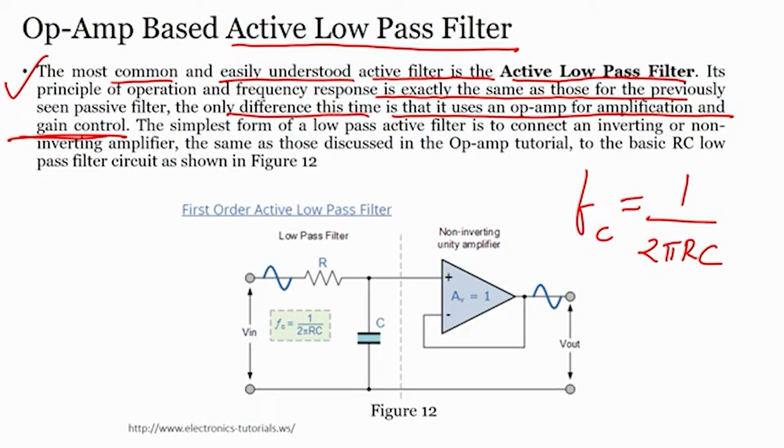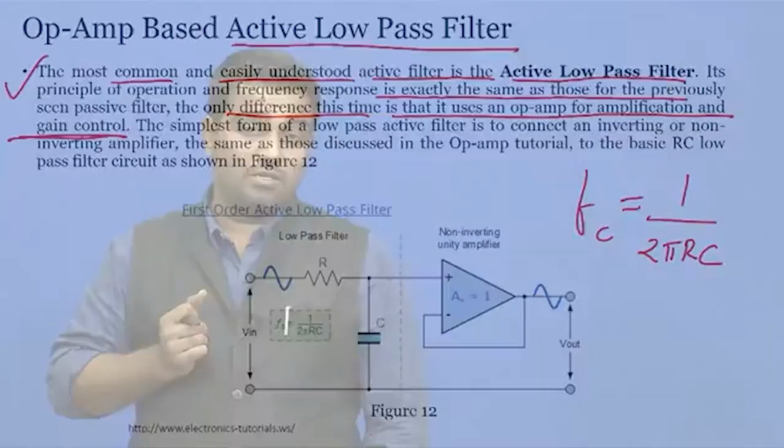Second thing we have seen is that it cannot be operated when it is less than 1 megahertz. That was the case of passive filters. But when you talk about active filters, you integrate your op amp to the RC, and because of the integration of this op amp you can adjust the gain and also tune your filter. This kind of active filter is used for frequencies both below 1 megahertz as well as above 1 megahertz.